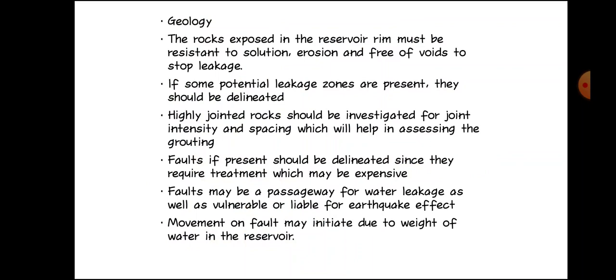Geology. The rocks exposed in the reservoir rim must be resistant to solution and erosion, and free of voids to stop leakage. If some potential leakage zones are present, they should be delineated. Highly jointed rocks should be investigated for joint intensity and spacing, which will help in assessing the grouting.